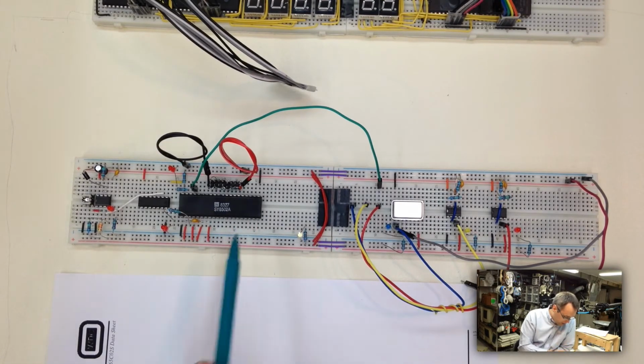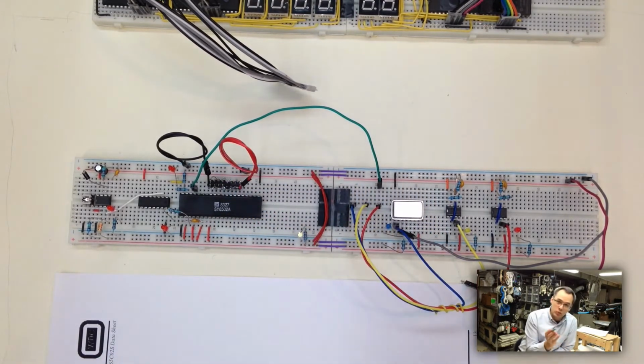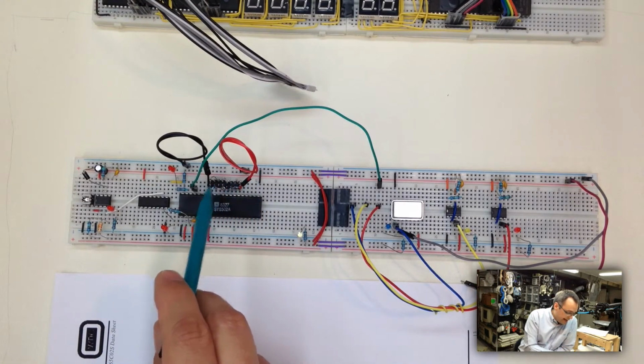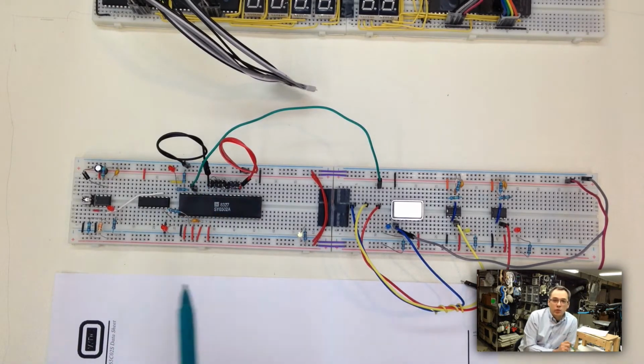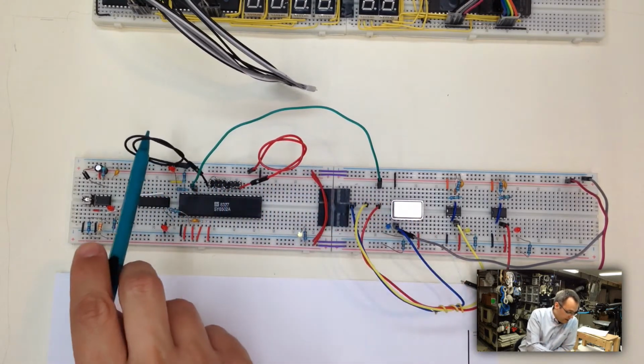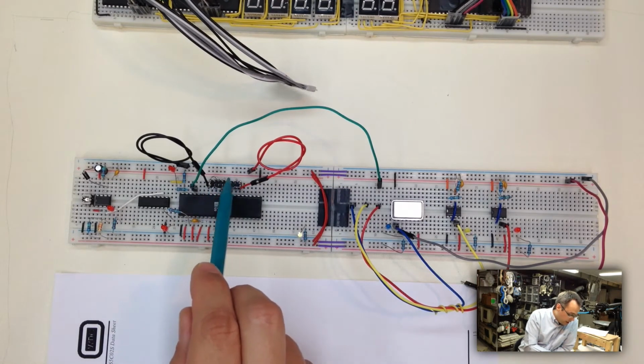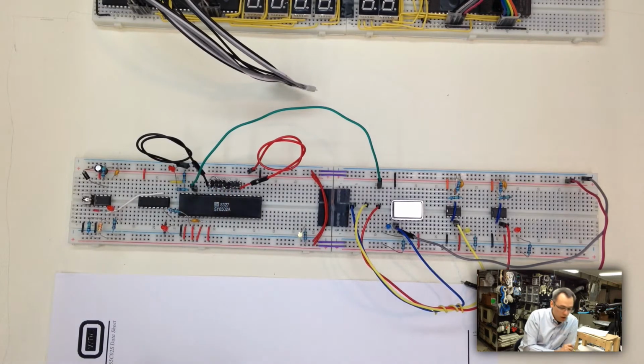The rest of these pins here are the address bus. Nothing's connected to those right now. We'll be getting to that soon. Again, 4 pins here, address bus. These pins right here are the data bus. We got a funky little connector on here. Normally, these would be connected to a data input from RAM or ROM. But because we don't have RAM or ROM in this computer, we've got to feed the CPU something. It's a little bit hard to see, but basically this is hardwired to 11101010. The red's on this side, the black's on that side. When you convert that to hexadecimal, that is the character EA. Keep that in mind if you're a 6502 programmer. You know what that means. If you're here along for the ride, I'll explain it in a little bit.